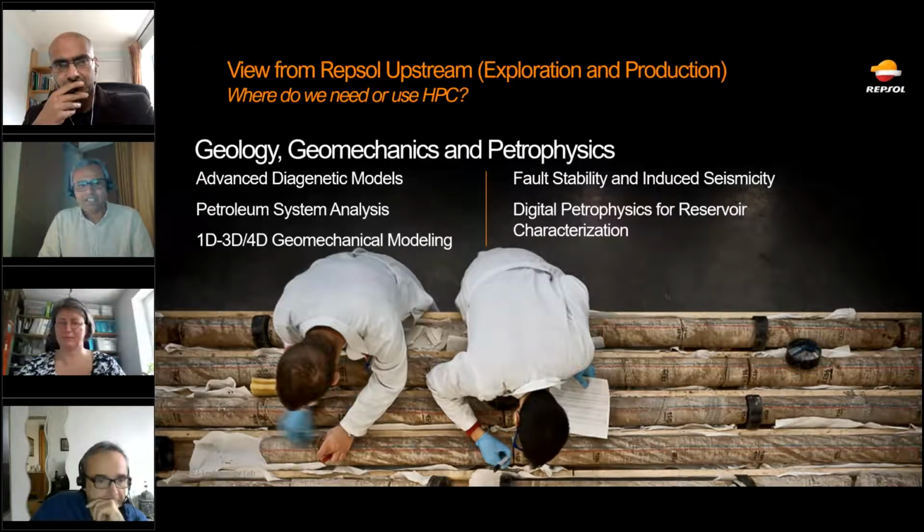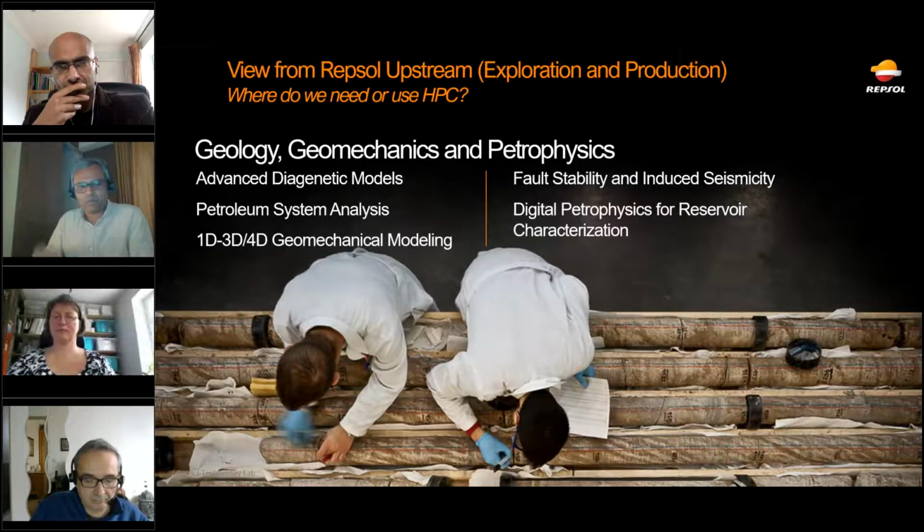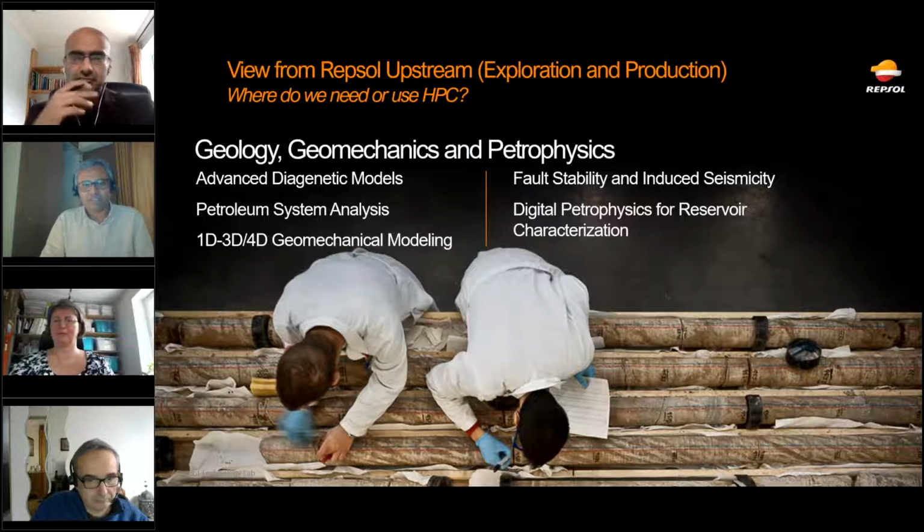Just to give you an example, imagine a piece of rock, maybe a shale rock from an unconventional reservoir, with pore sizes of nanometers. If we want to assess the pore size capacity and how the hydrocarbons or the fluids are going to move internally, we might end up doing experiments for several months, sometimes 6, 7, 8, 9 months, to have complete saturation and then find out the properties. Instead of that, you can use medical grade or even better CT scans, high resolution electron microscopes, SEM, FIB-SEM, all these images, and then you convert these images into a mesh, and you will be able to do something called